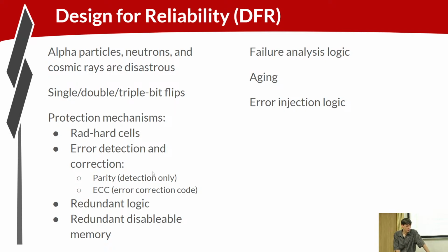So that's generally the approach for memory. Other approaches for protection: rad-hard cells are your big hammer. Mostly it's the flip-flop states that we're worried about because those are holding values. They're more susceptible, more likely to impact functionality. You can have cells that are just more robust and less subject to flipping. You can use those cells if you can accept the area impact.